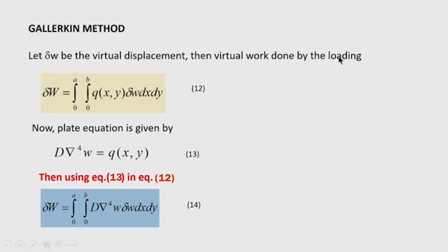Then the virtual work done by the loading is del W equal to a double integration, which is required because the plate is extended in x as well as in y direction, and q(x, y) is the load applied on the plate and del w is the virtual displacement.